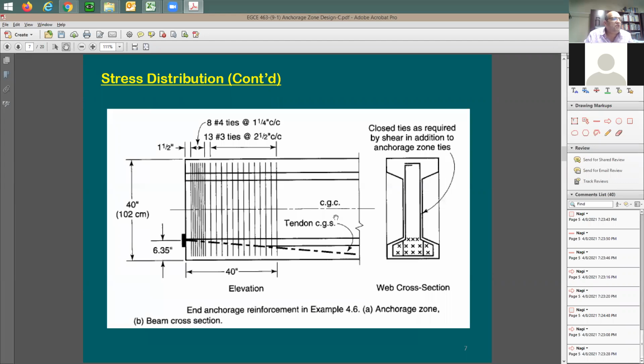I'm going to show you here a picture of the beam. So here's the beam. This section here is going to be like an I section, and usually at the end it's going to be a rectangular section. But in this beam detail, you see that there is no rectangular section at the end. It's just kept like that. This is the way it was designed. So these two lines are just straight. And look what happened. Usually, I would expect that this section here is where the I section is, and right here, most likely, is going to be the rectangular section, which means this section right here.